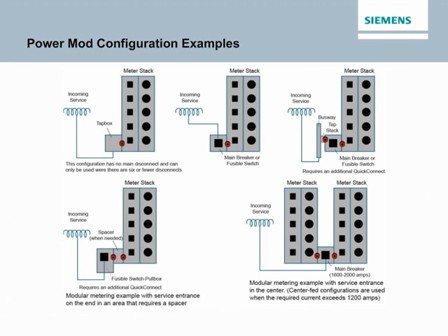The accompanying illustration shows a few configuration examples. Other configurations are also possible. For simplicity, only 1 or 2 meter stacks are shown for each configuration, but additional meter stacks can be added as long as the cross-bus and main device specifications are not exceeded. Utilities have varying requirements for equipment height, cover types, and bypass types. Therefore, utility acceptance should be obtained prior to installation of any modules.